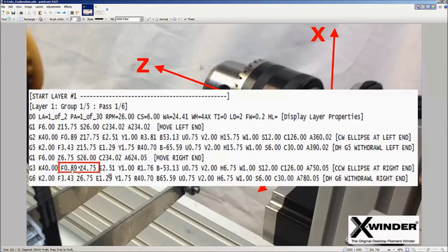That is the carriage speed that will result when the carriage reaches a Z coordinate of 4.75. So through these 2 inches, we went from 6.75 to a Z of 4.75. We're basically going to linearly reduce the speed of the carriage from 6 inches per second down to 0.89 inches per second when the carriage reaches the Z coordinate of 4.75.